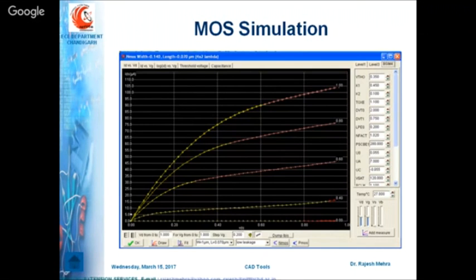For example, you are creating one XOR gate, and you want to view the output based on your two inputs, and that is the logic. As per the truth table, you want to compare your result, and in that case level 1 is okay. You can check the behavior of your circuit. But if you want to check the rise time delay and fall time delay, that is not possible.